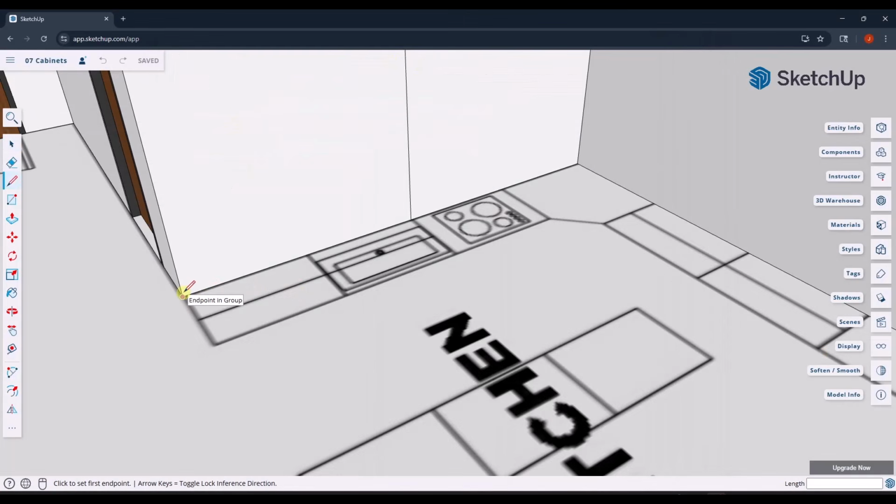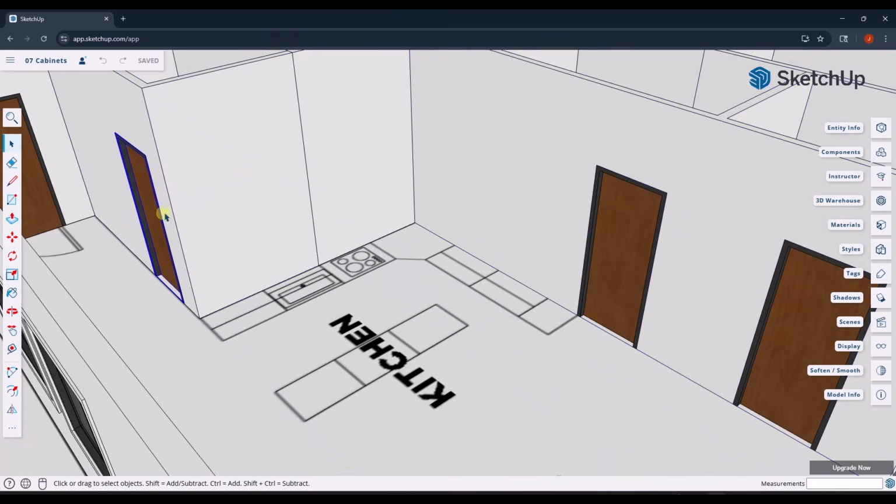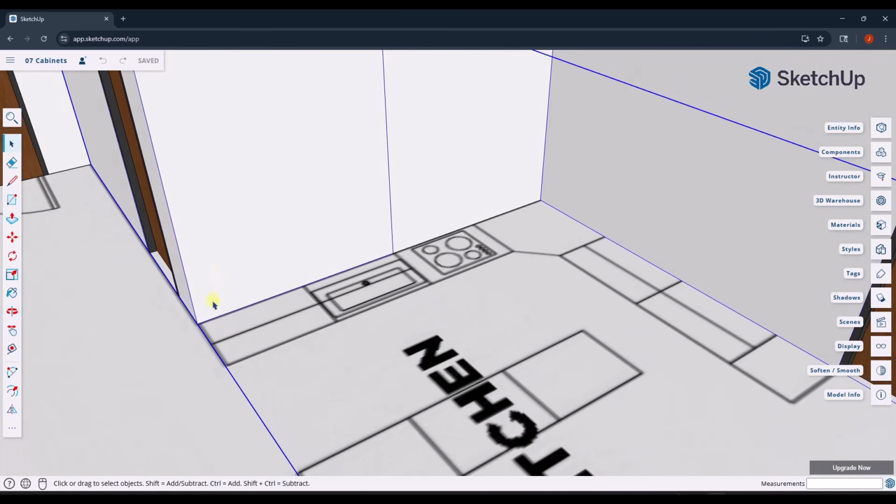And so we'll just assume that our cabinet base is going to be 24 inches deep, right? So what I'm going to do is activate the Line tool by tapping the L key. And remember, it's important that you've tagged all of your walls and doors so that you can toggle them off, and also so that they're not going to be merging with this geometry in here.